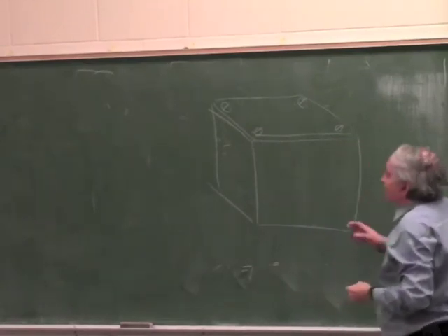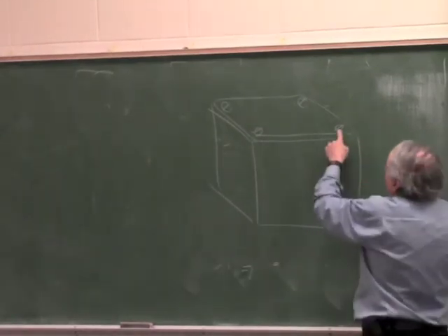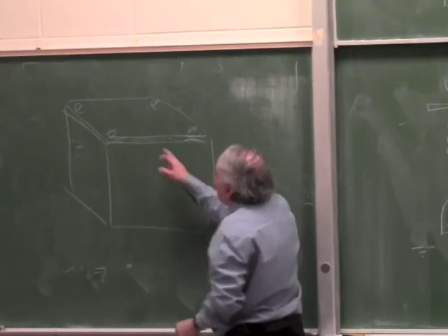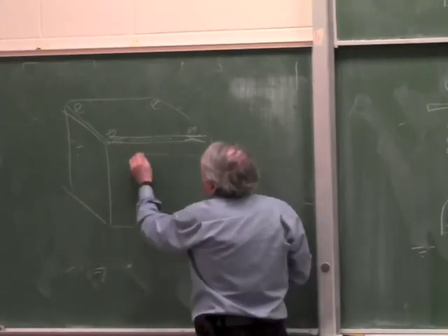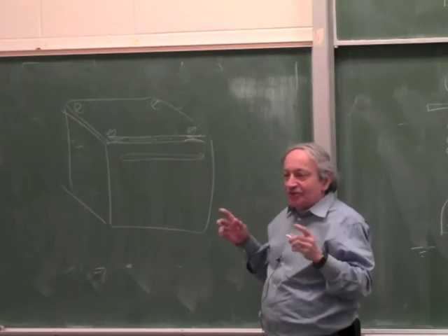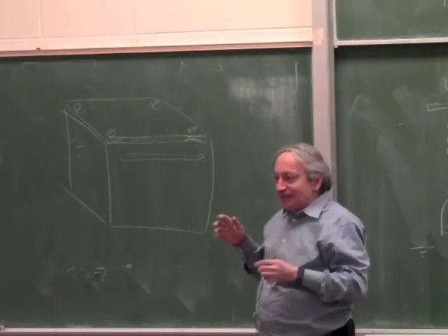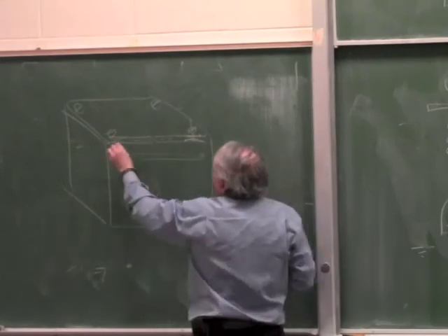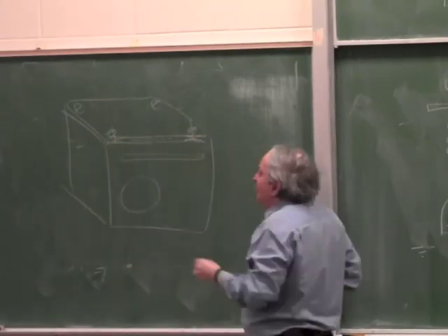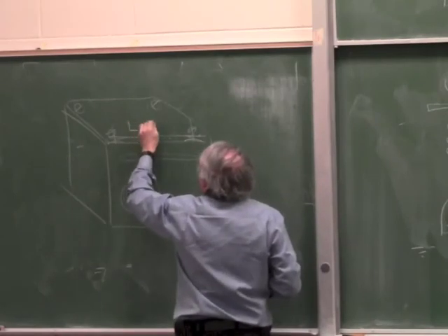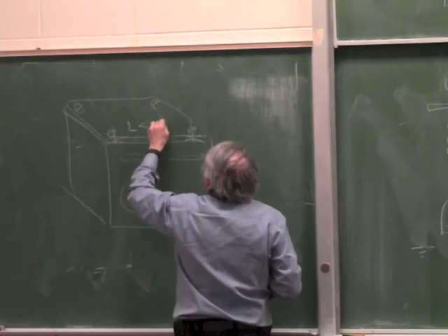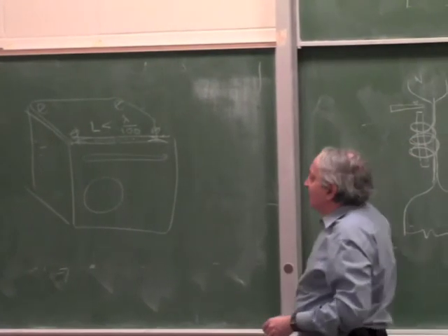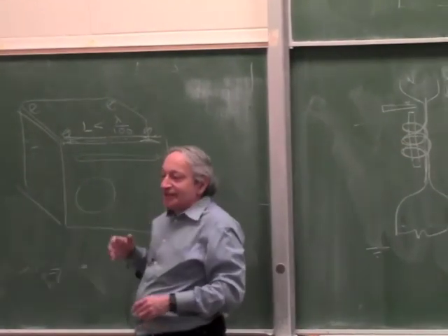But if you're dealing with very high frequency, this may not be sufficient, because the 4 screws will guarantee electrical contact where the screws are, but there may be no electrical contact here, so it will be the same as having a slot. And if that slot is big, it can act as an antenna. An electromagnetic field can come out. So basically any kind of holes or slots or distance between screws, which is same as grounding points, this dimension L has to be smaller than lambda over 100, otherwise it doesn't work. Because anything which is not continuous ground can act as an antenna.